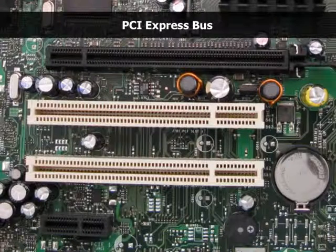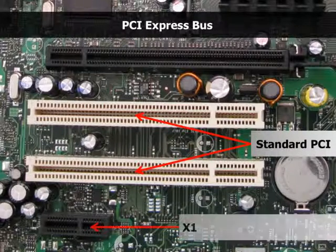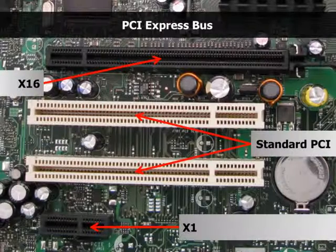And here you see an example of the PCI Express bus. It's not backward compatible with the PCI standard we showed a little bit earlier. It uses a serial bus to send data, and each PCI slot connects directly to the south bridge. You have a number of different sizes that are available. You have X16, this is standard PCI. You have an X1 that you actually see there. You have X16, and so forth.